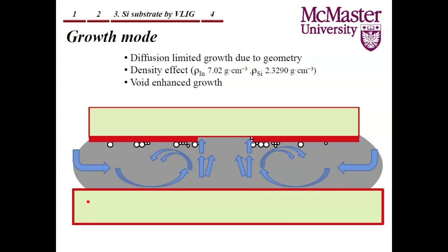seed line region. But because of the presence of these bubbles, and these bubbles are the hydrogen bubbles pre-existing at this oxide layer, keep in mind that the oxide layer has a poor wettability with this solution, the hydrogen bubbles will coalesce at the interface of these layers, preventing any deposition of silicon in this region. That's why we have this gap mechanism in between.